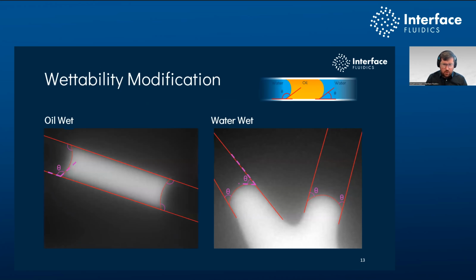And before I mentioned how important it is to get wettability correct. Wettability is a primary impactor on recovery, as we all know. And so making sure you get initial conditions as well as representative reaction from the porous media is very important. And so what we have is the ability to tune the wettability of our microfluidic systems to be representative of our clients' reservoirs. So if you're looking at an oil wet reservoir versus a water wet or something intermediate in between, then we can tune our system to be representative of that.